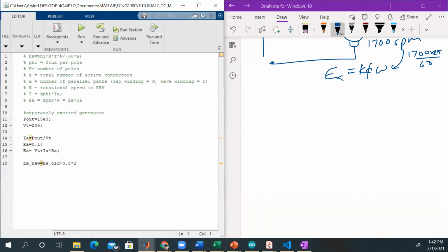This is a short question. Okay, so we have this time a 2-pole separately excited DC generator with full load conditions, 200 volts, 15 kilowatts, 1000 RPM. Find the generated EMF when the conditions are altered such that the flux is reduced by 20% and the speed is doubled. Also find the output power for a current of 50 amps at these new conditions, RA 0.1 ohms. So this time, we have a generator,